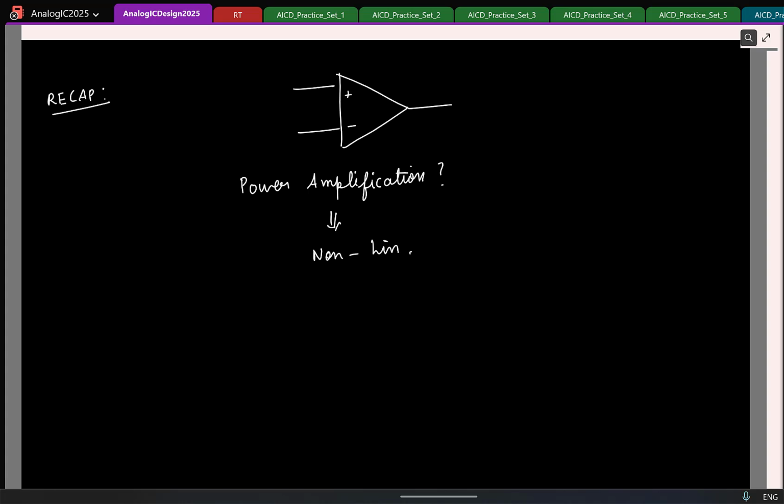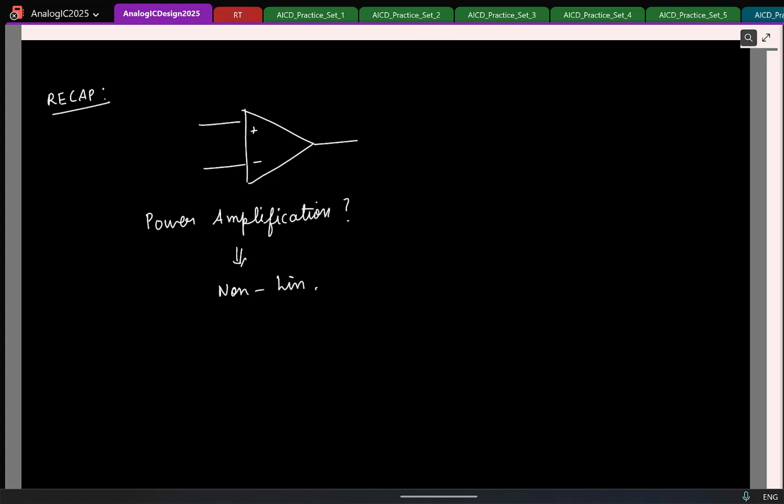And we started with a single port nonlinear network, and although the network is nonlinear, for small signals, how can you treat the network as linear? And if it's a single port nonlinear network like this, for small signals, how can you model it as a resistor? So if the current is some f of e, what will be the value of the resistor? 1 by the first derivative at the operating point, right?